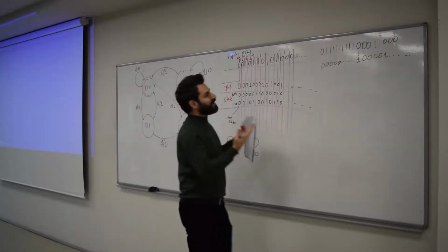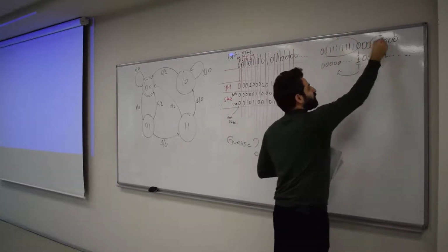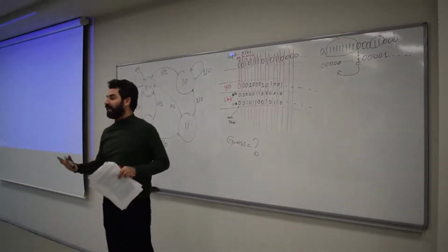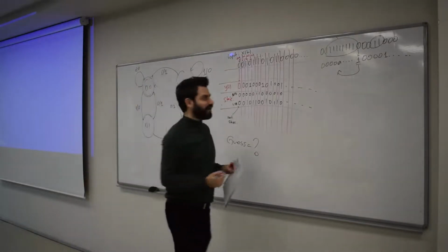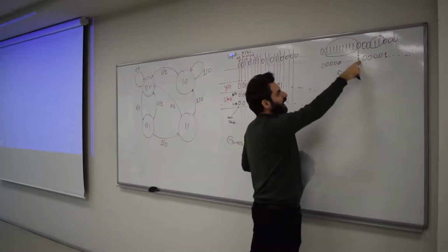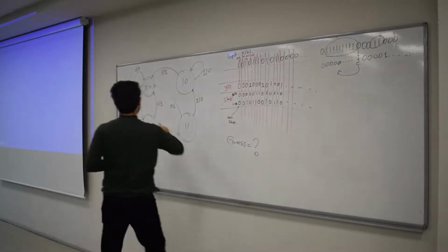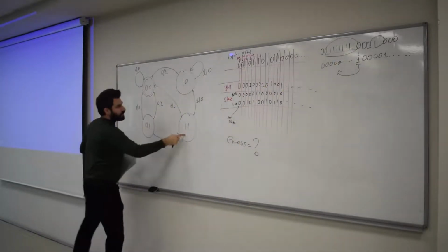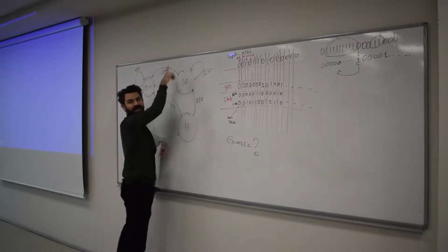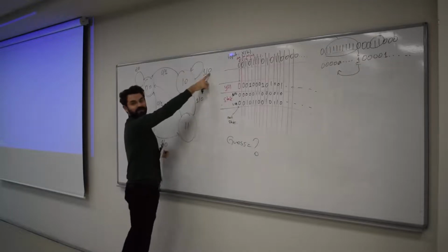Okay, so what does that mean? These ones are pushed out because of these groups of ones, right? There are piles, and there is a specific name for that, runs of ones. Okay? So there is a specific run of 1 here, right? And that one actually is generated because of those runs of ones. See that one? You see, you got a 1 here, 1 here, 1 here, and as long as you have got 1 in the input, you will stay in this state for as long as you see an input 1. Okay, and that generates always a 0.